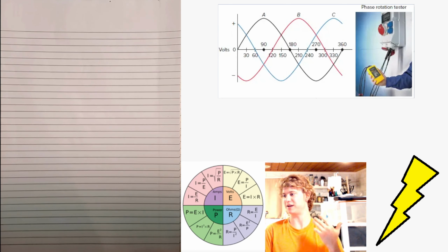The power delivered by a single-phase source is pulsating, whereas the power delivered by a three-phase system is relatively constant at all times. We're going to talk about this in a second. This means that even though the power in each phase is pulsating, the total power at any instant will be relatively constant. Therefore, the operating characteristics of three-phase machines will be superior to single-phase devices with similar ratings. A motor or transformer may be the same physical size, but the horsepower rating of three-phase motors and the kilovolt ampere rating of three-phase transformers are 150% greater than for single-phase motors and transformers.